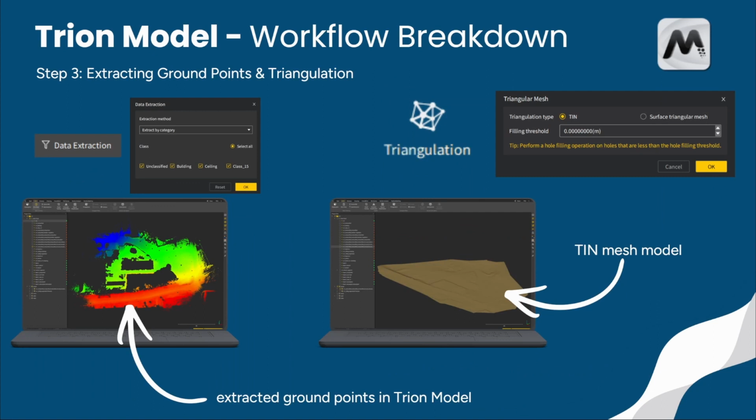Once we have that, we use data extraction to export the point cloud by class and create a new point cloud containing only the selected ground points. At this point, because we have removed disturbing elements, such as buildings, trees, vehicles, or stockpiles, there will naturally be gaps in the dataset.